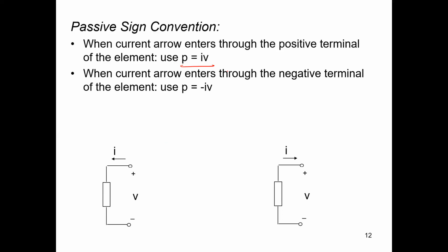An element refers to a part of a circuit. In this case, it's this little box here. That box is a circuit element. It could be a battery, like the battery you're trying to charge in your car, or it could be a resistor. It's an unmarked box, an unknown element, and we don't care. All we need to know is the voltage at the terminals and the direction of the current. From those two things, you can tell whether power is flowing into or out of this box. And that's really good to know, right?